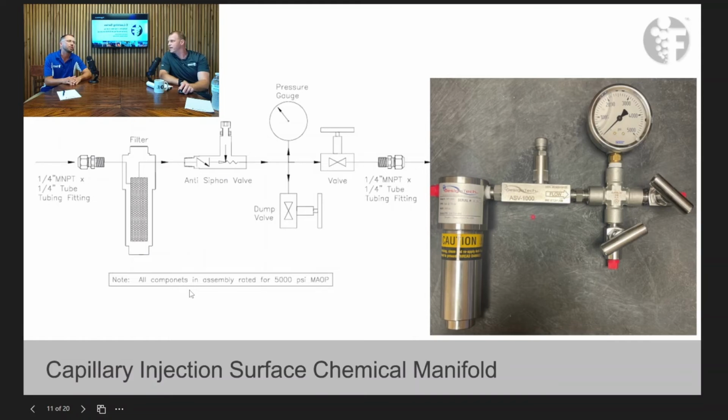You have to. And it's very important to keep in mind, again, I pointed out the filter being longer. It's very important that you have a good filter, because you've got to remember this is what's going in your well. It's got to pass through that filter. Sometimes, if a guy forgets to clean the filter, that longer filter will keep more debris in it until somebody remembers.